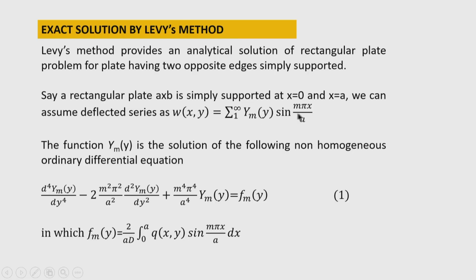The most fundamental thing in Levy's method is that the deflection is assumed as a sine series, that is, we have to assume the deflection surface as a single sine series. The summation extends from 1 to infinity, and the deflected surface is taken as a function of y multiplied by a sine function, sin m pi x by a. Here it is sin m pi x by a because of the edges x equal to 0 and x equal to a, that means edges parallel to the y axis are simply supported. Therefore, the sine function is taken.